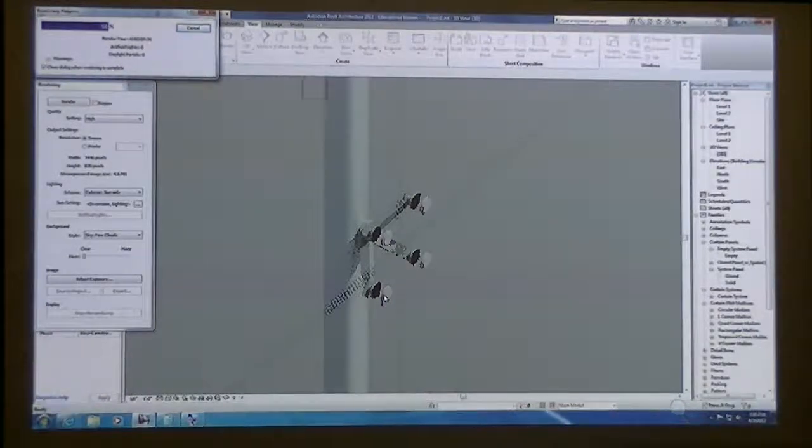And if you really wanted to get more detailed with this, what I've seen people do, and you can kind of see in the rendering here, you do see the edges of the glass, but I've seen people take that glass panel and add a little black edging to it, so you get kind of the sealant look. And then you can get the divisions of your glass a little bit better, or you can gray it out or something like that. So there might be some additional items to model in there eventually.